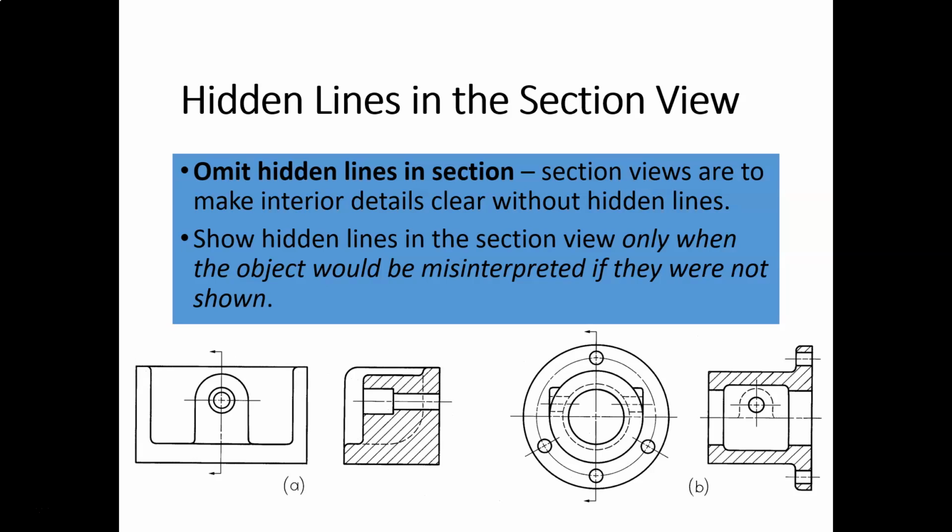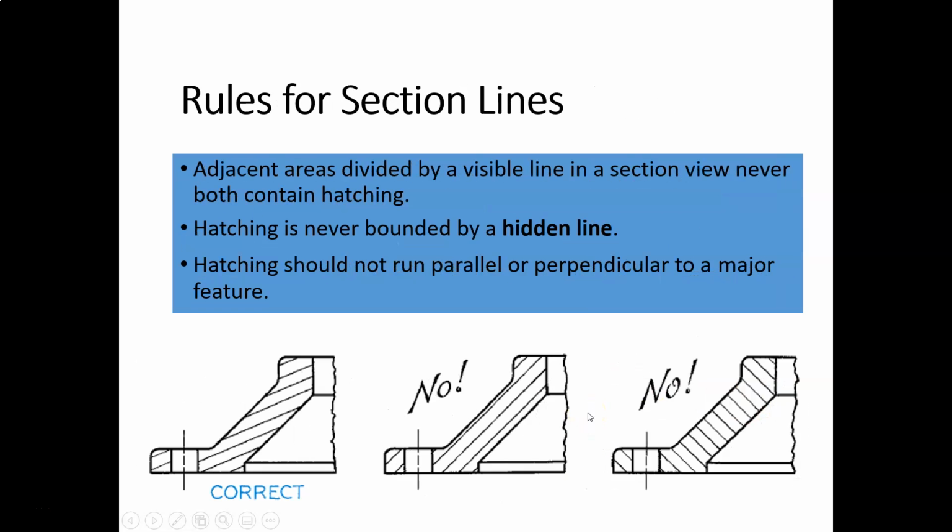And once again, as I said before, this is your section view. Not this. This is not your section view. This is the view with the cutting plane line. Again, this is your section view, not this. This is your cutting plane line. So if I show hidden lines in this view, yeah, absolutely. You have to. Boom, they're there. Hidden lines in this view, probably not. Section view, not section view.